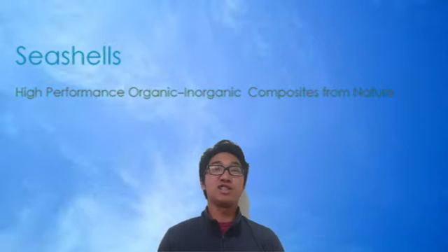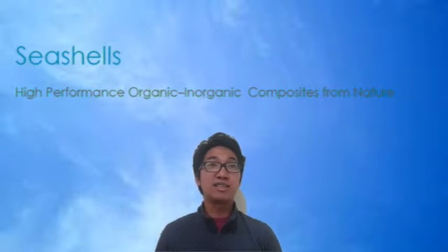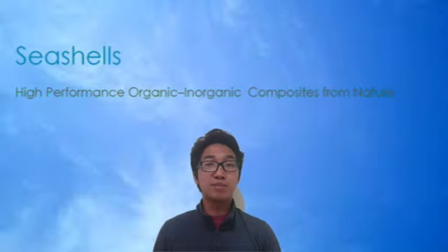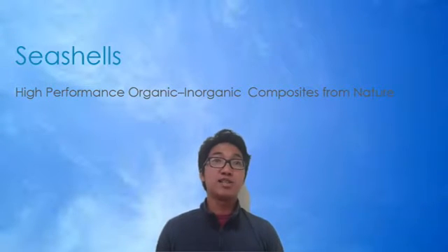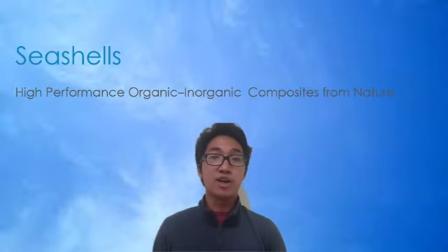And the next one is the seashells. It is a high-performance organic and inorganic composite from nature. The shells of a mollusk exhibit exceptional toughness despite being composed of brittle inorganic cells. The mechanical strength of these shells can be attributed to these molecular interfaces as well as the complex hierarchical structure consisting of ordered lamellae or layers.